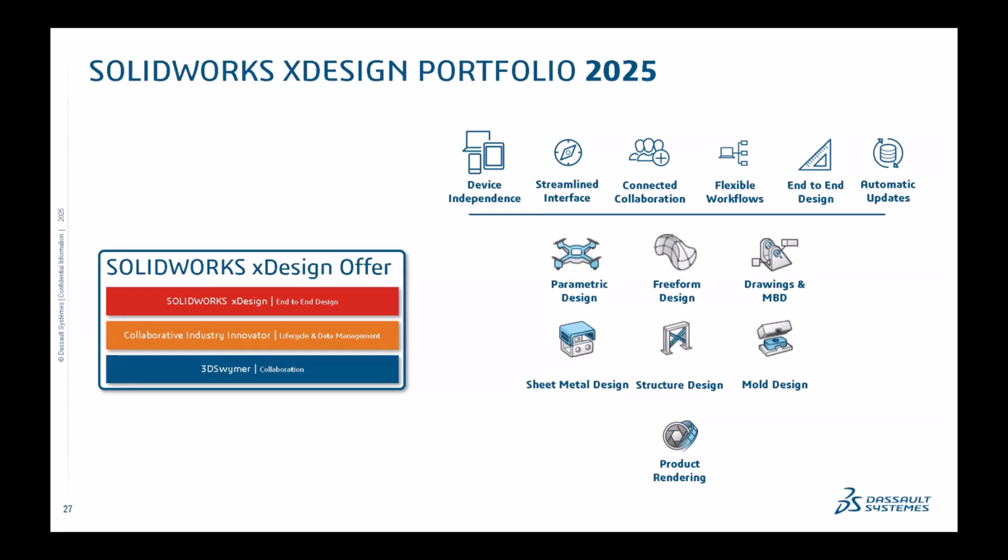There is another application called xDrawing that allows to create drawings from a browser, but it's a special application because when you create a drawing, it will automatically create also the MBD. So it creates annotations on the 3D model organized in views that can be used if your final customer is a company that doesn't want a 2D drawing but wants an annotated 3D model.